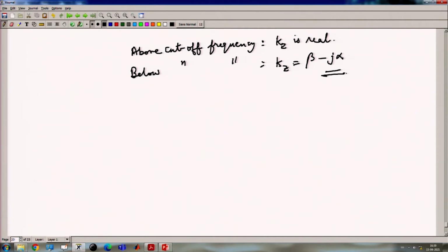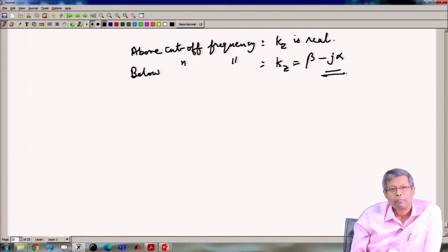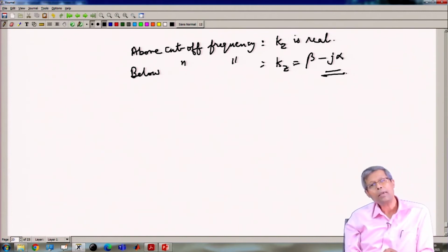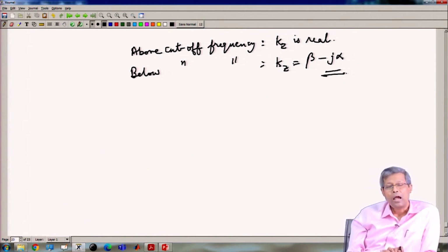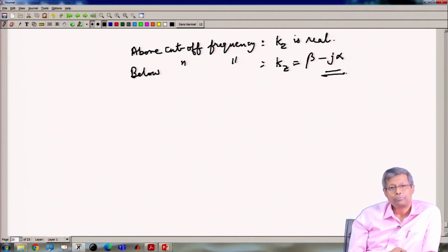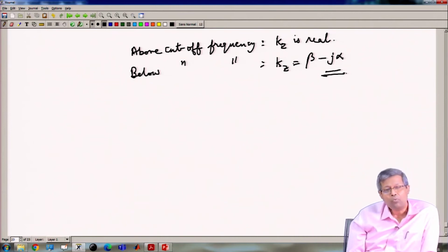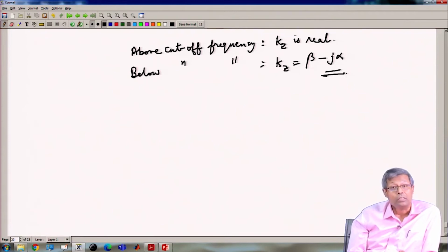So, therefore, the dielectric guides operating below cutoff can be used as antennas, because they are radiating energy to free space. I can make the same dielectric strip or dielectric guide operate as a guided wave medium with Kz real above cutoff, which are essentially called surface waves inside the dielectric, or I can make it work as an antenna, so that these waves have a complex propagation constant.